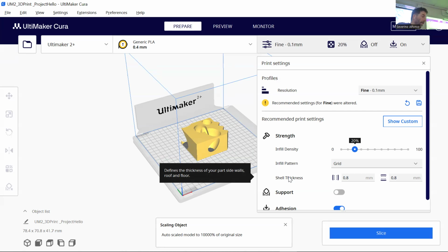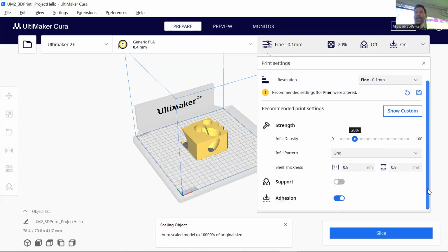So the bigger it is, the more detail oriented it is, and the thicker that layer, that shell, is. No? So in general, I would keep the defaults for your first settings of models, and then learn from the results of your first test.